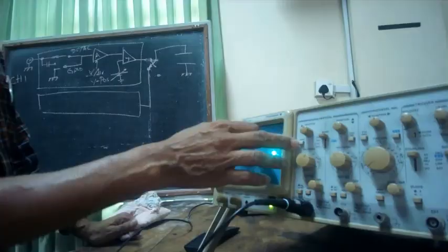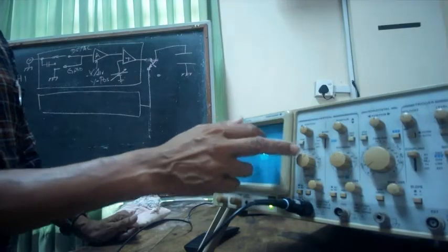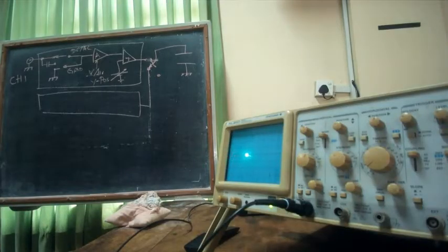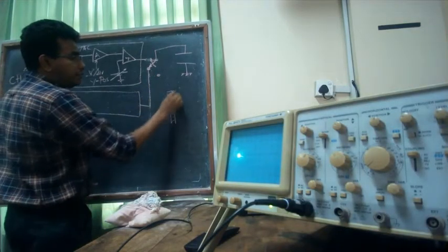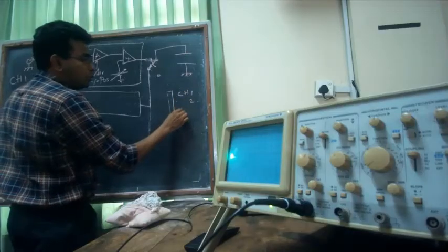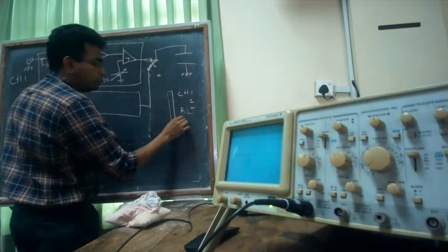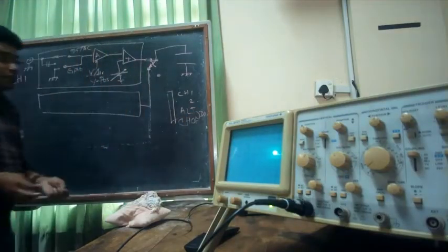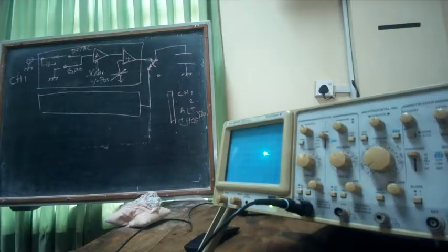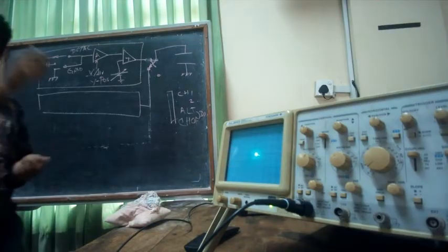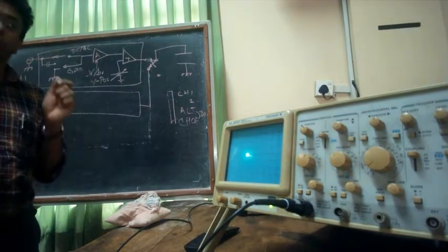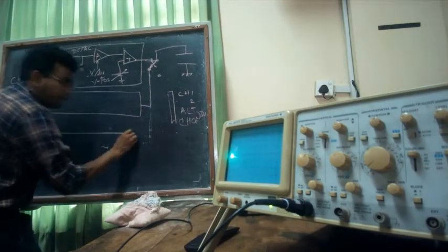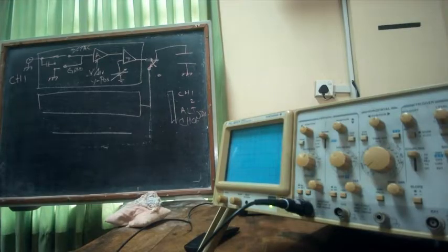Say, for example, there's another button called chop, sometimes on the mode selection also, right? In some you have CH1, CH2, alt, chop. These are called dual. Alt means you apply the signal during the whole sweep from here to there for channel 1.